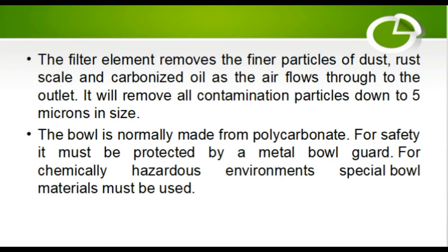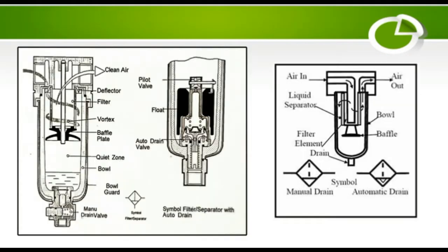The bowl is normally made from polycarbonate. For safety, it must be protected by a metal bowl guard. For chemically hazardous environments, special bowl material must be used. This is a picture showing the airflow.